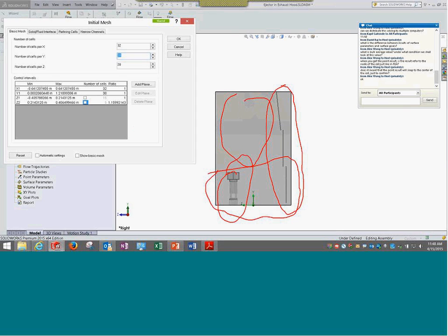So what I do is I give the location of the plane. Between 0.64 and some other values and this one, I'm saying there are 32 cells. In the Y direction, which is taken as Z, now in terms of Z we have a bit more segregation. That is, it is from the values given here, but I'm selecting a few more points down here.